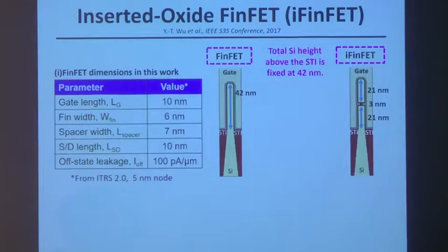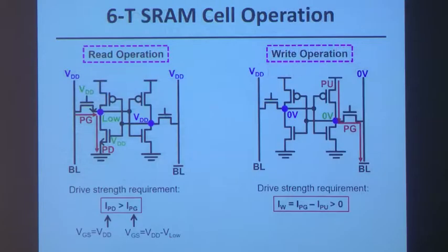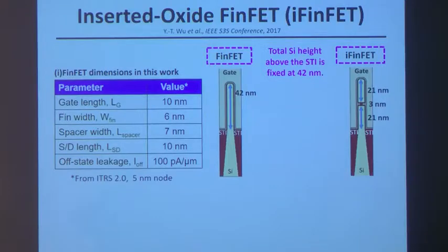Okay. So fundamentally, then, how do we continue Moore's law, scale the size down, to fit more transistors or more cells on a chip, have more functionality for a chip, and get around this problem? Now, with a FinFET, you really can't change the channel width, the effective width, very easily. You can change the number of fins.